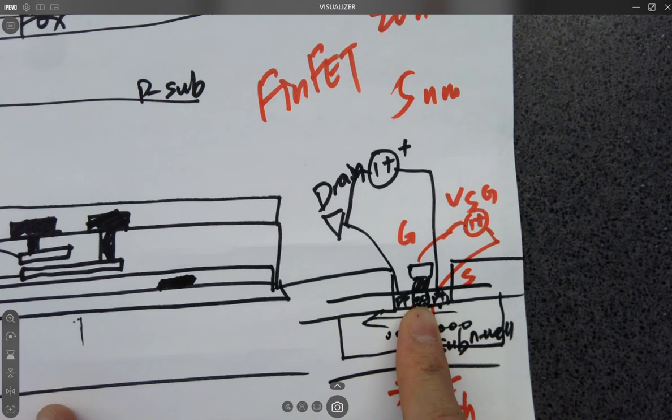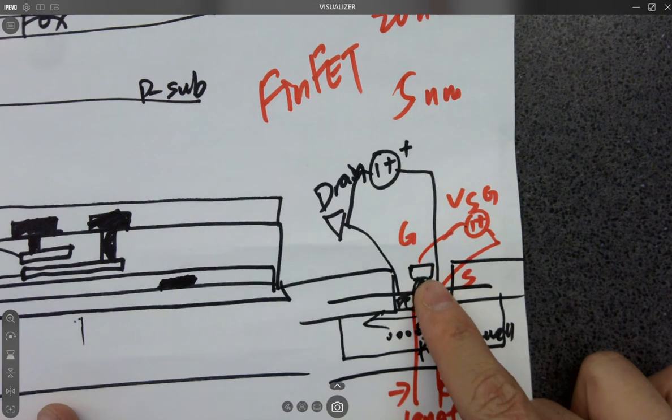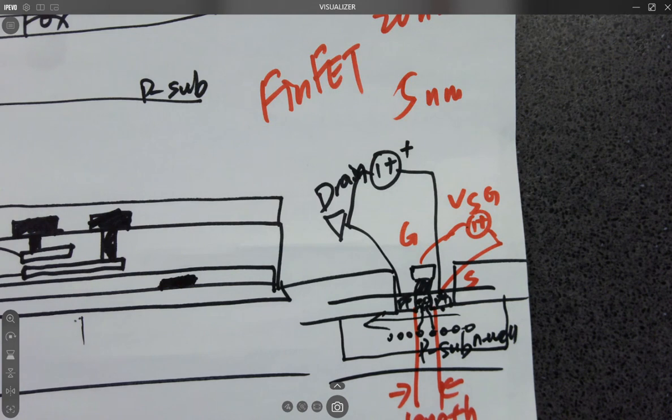So in that case, there's new technology called FinFET getting developed. You cannot just directly place something on the top to provide electric field. You have to wrap it. You know what I mean? So for example, if the stack of paper like this was a channel, I can have a little gate on the top to provide the electric field to run current through the paper, okay?